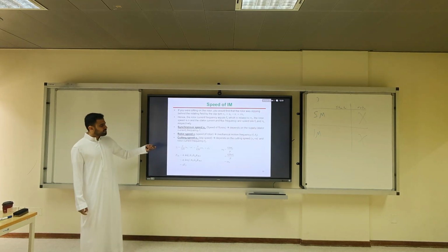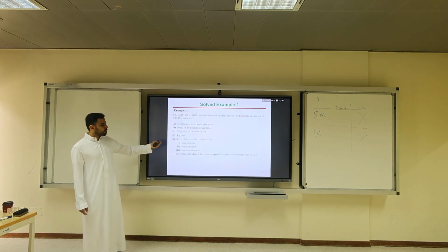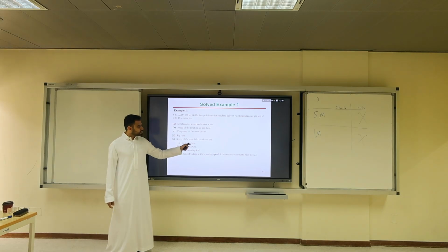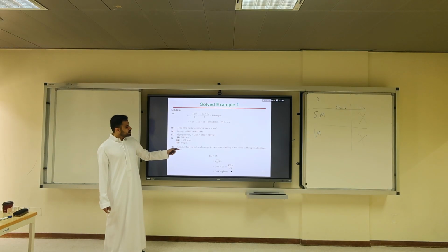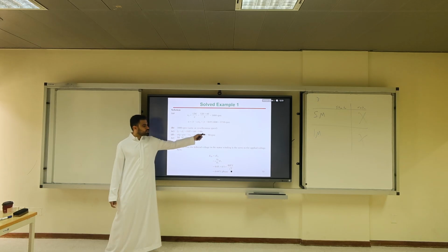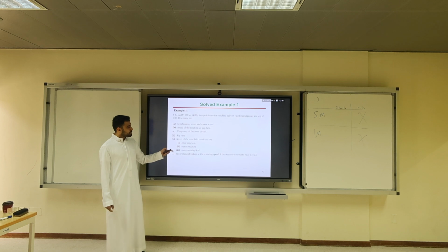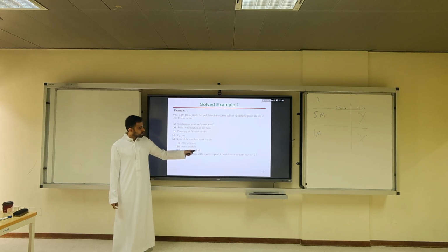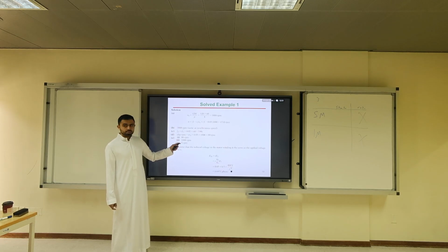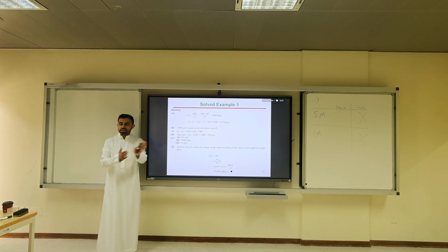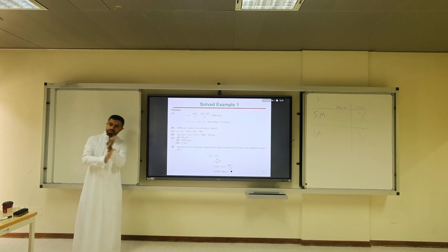So to solve this problem, the author of this textbook thought about it, and measures it with respect to the rotor structure. He is saying it is 90 RPM, which has to do with the slip. Relative to the stator structure, it's 1800 RPM. Relative to the stator rotating field, RMF, it's 0. Does it stop moving? No, they move the same speed.